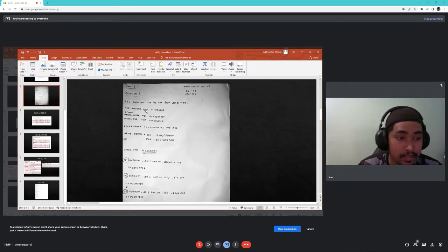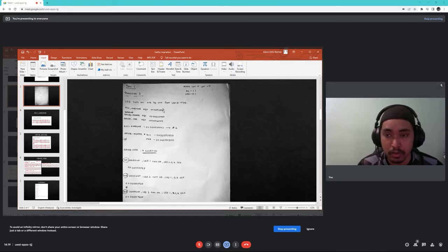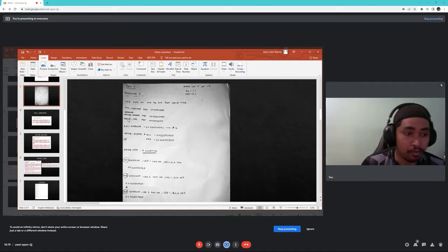We can find it inside the formula, which is fixed: the RCC register, GPIOB MODER, and GPIOB ODR. If we want to put it in our Keil or inside our coding, we need to declare this first. This is fixed. We can find it in the formula, search for it on the internet, or remember it.